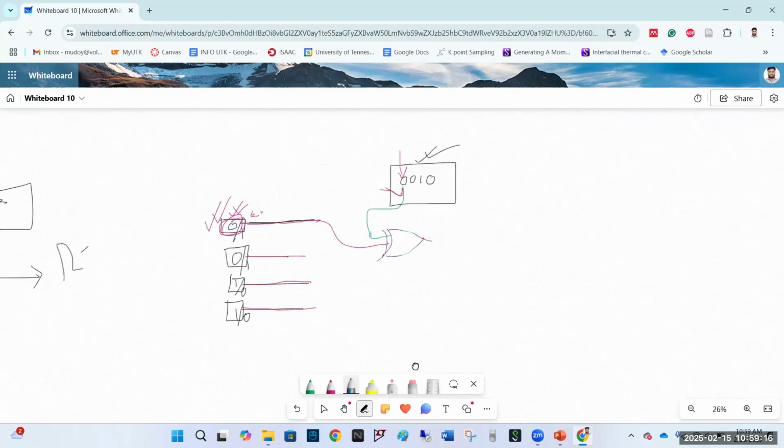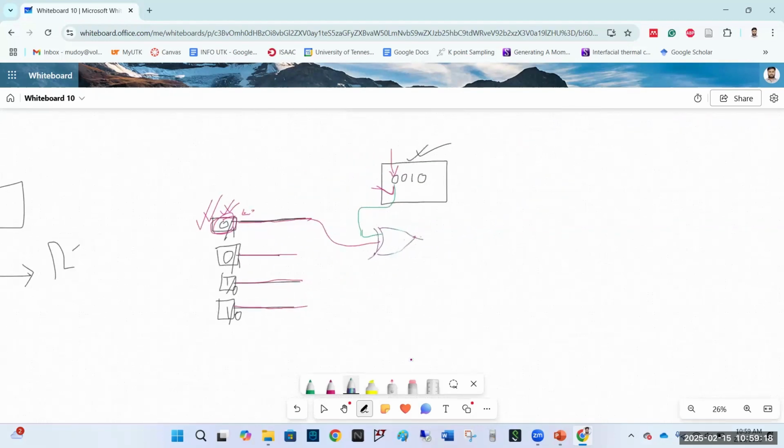But unfortunately, in our Tinkercad there is no XNOR gate, but there is an XOR gate. We can easily make XNOR from XOR because we have an inverter. If we insert an inverter at the output of XOR, it will be XNOR. The same can happen in the case of AND gate. We have AND, we have NAND, right?